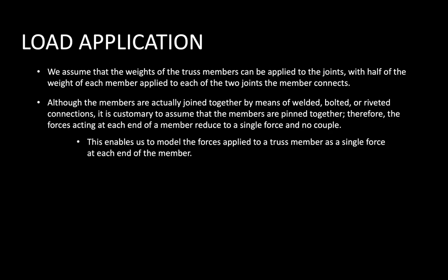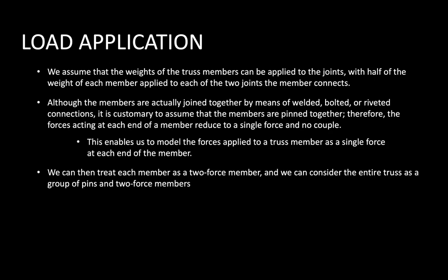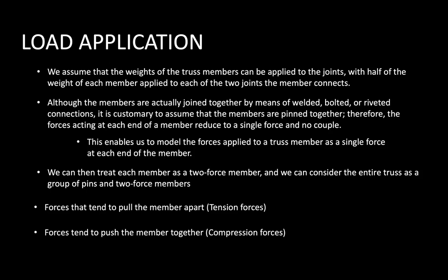This enables us to model the forces applied to a truss member as a single force at each end of the member. We can then treat each member as a two-force member, and we can consider the entire truss as a group of pins and two-force members. Forces that tend to pull the member apart apply tension forces, while forces that tend to push the member together are compression forces.